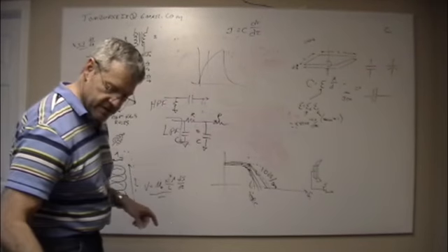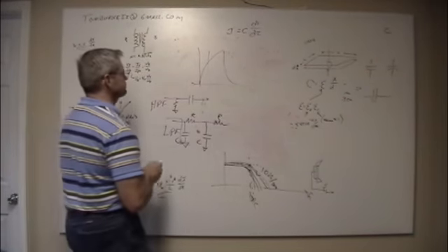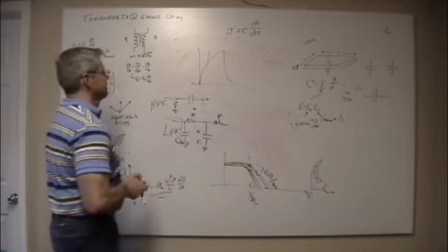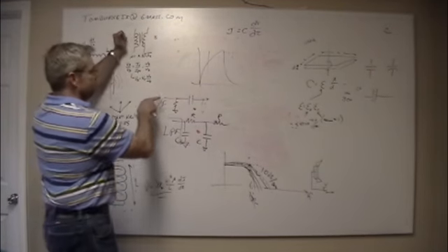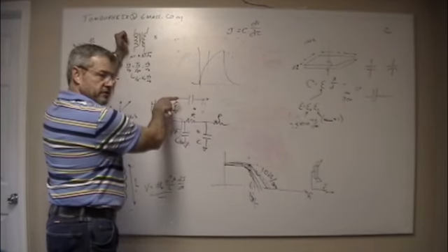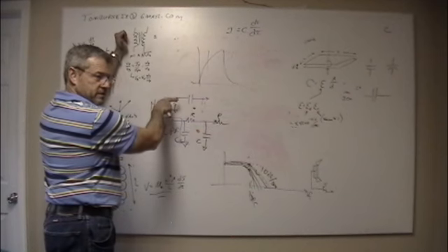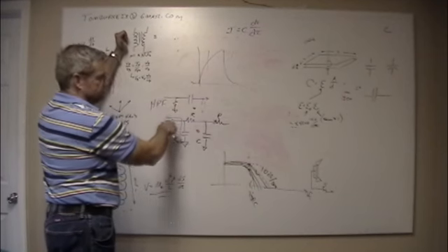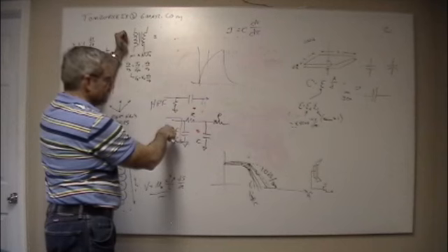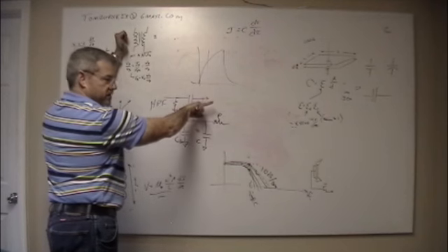The flip side of this is red. Think about this. What happens here? Low frequency stops. It doesn't go through, right? Because the capacitor blocks it. So it just kind of goes to ground through the resistor. High frequency, on the other hand, zips right through.